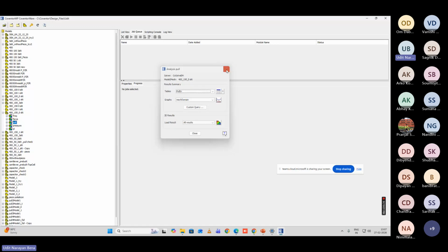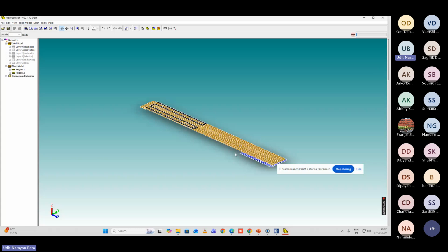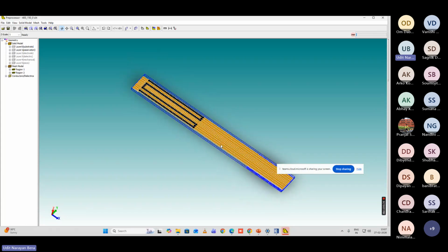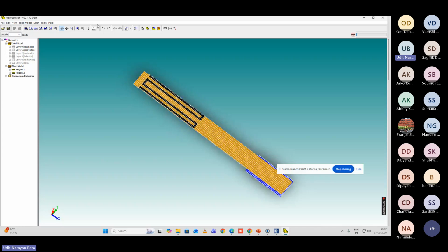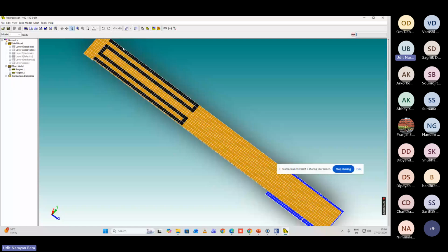So once these are done, let me show you if you have a piezoresistive cantilever, very quickly, I will take 5 more minutes. Here, this is another cantilever, similar cantilever, but you can see if I zoom it, that there is a black layer on the top of your cantilever. This black layer is nothing but your piezoresistor that is made up of doped silicon or polysilicon. Now, the first question, why is it here? Because you have just now seen that the maximum stress is in this region only. So that's why the piezoresistor is placed here.